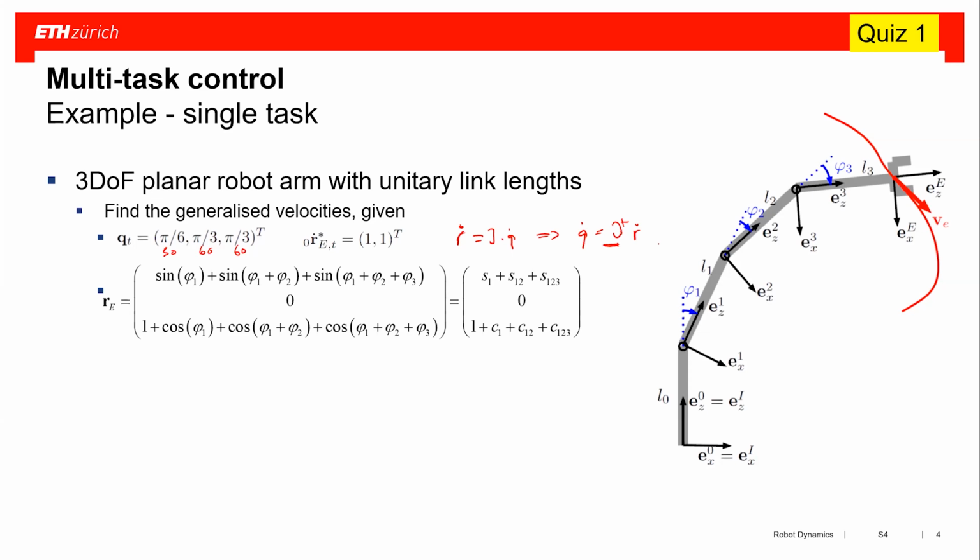There was a question which is whether or not we should always take the pseudo inversion even if the Jacobian is invertible. If the Jacobian is invertible, then the pseudo inversion will give you the same result. So if it's invertible, you have only one solution, and then you can take this one solution. The least square optimal solution of that is the same solution. So that will not change anything.